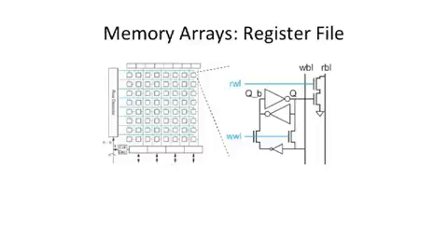In order to have this work, we're going to energize or ground the write bit line such that it's stronger than what either of these inverters can drive. So we overpower the inverter, and we can flip it, let's say, from a 0 to a 1 or a 1 to a 0. So this is not traditional complementary logic, but this is how we typically build register files. Small little arrays that are close, let's say, to a processor.